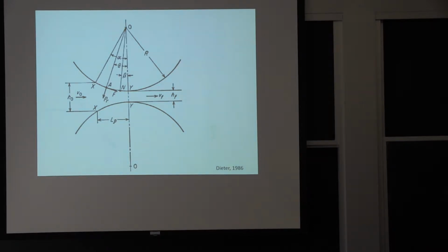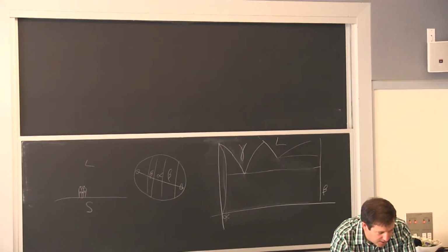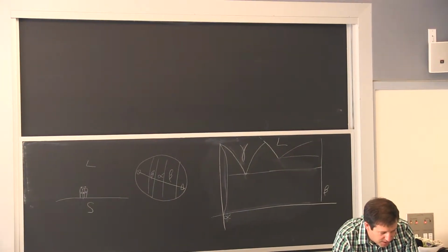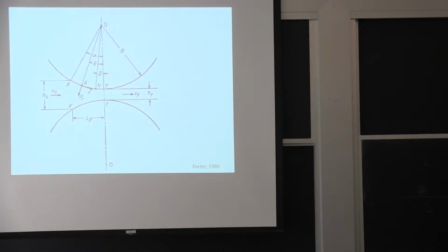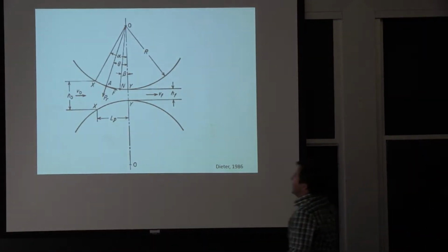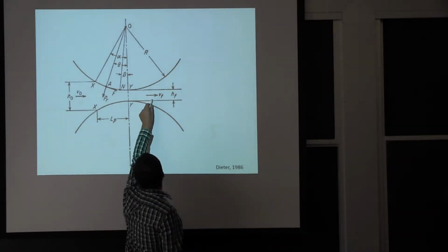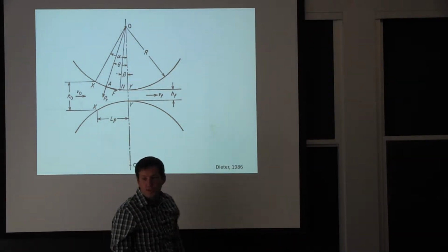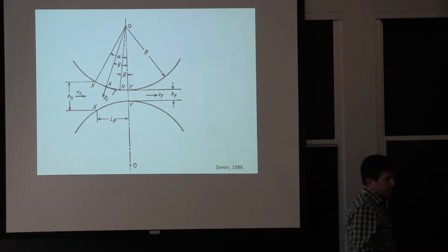The first reason is conservation of volume. So if I'm looking at this as a sequence, I have something that's very thick that's thinning down on the image. I'm exaggerating a little bit. This is a factor of 2 reduction. That's a little high. But the idea is the speed here, in this case, is twice what it was over there. It's not exactly realistic, but again, the work pieces just keep going faster and faster.